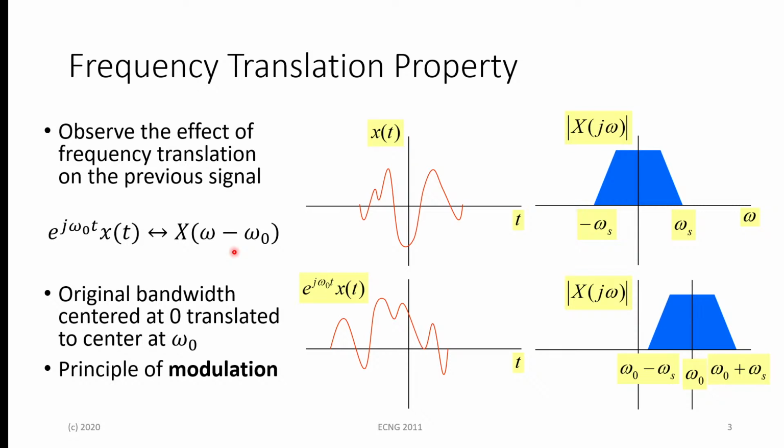And after your voice is transduced from an analog signal to a digital signal via the microphone and so forth, before it can actually be transmitted onto the wireless carrier range, so let's say if it's a cell phone signal using GSM, that means that instead of the signal being in kilohertz, it now needs to be represented at megahertz, because GSM transmits at around 800 to 900 megahertz.